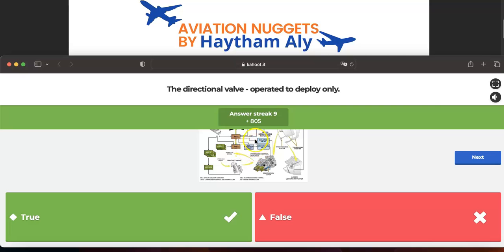The inhibition relay must be closed, and thanks to the engine interface unit and the second line of defense, the EIU will have the responsibility to energize the inhibition relay, so that the EEC can energize the directional valve.